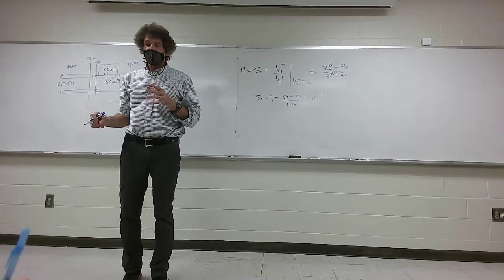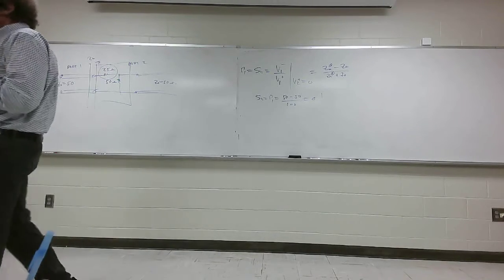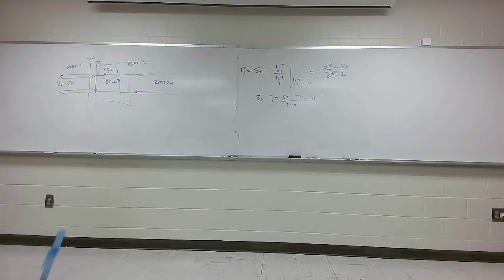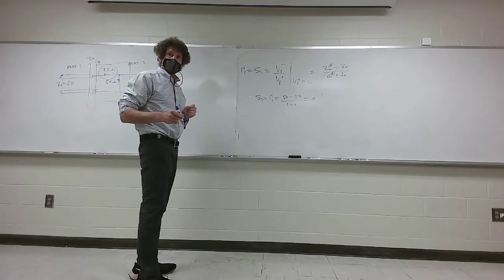A lot of times there's a minimal amount, and then with these S parameters they'll take 20 times the log of them, because when you get down to ratios that are that small, and you're comparing in the S parameter matrix something that's got a value of 10 or 100 for a voltage gain, then the scale is just way out of proportion, so they'll take 20 times the log of these quantities, the S parameters. Anyway, y'all agree that's 0?